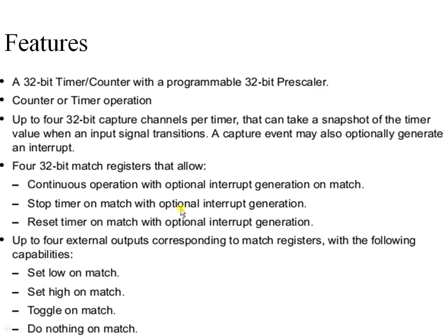Now let us start with the features of timers in the LPC2148. As you can see here, it's a 32-bit timer, and we can use it as a counter or as a timer, similar to the timers we have used in the 8051. So they can be used as timers or as counters in the same way, that is, delay generation or counting external events.